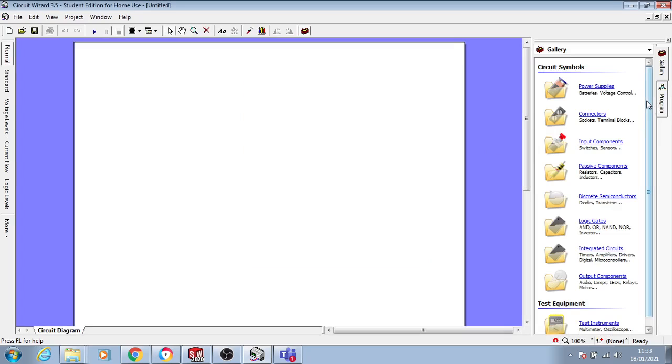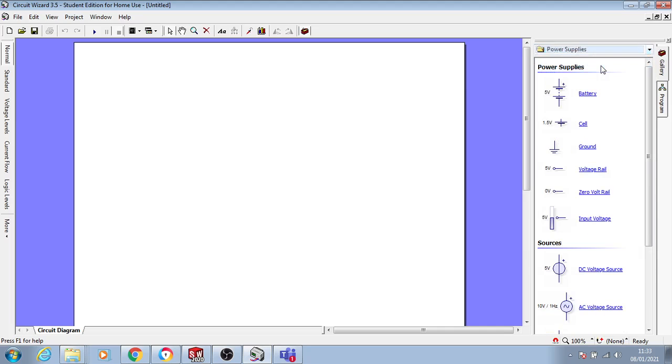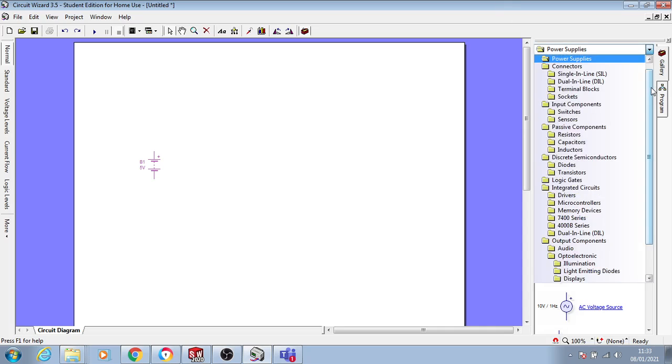As with the product design simple thing, we're going to need to connect up a circuit with power supply etc. So I'll go there and I'll just use a battery here, 5-volt battery. Now obviously I can draw a circuit. I can't actually finish this line, and I can only connect it up to something else, and I've only got a battery here, so I'll have to make a short circuit here to connect it. So best thing to do is, rather than burn out a battery like that, just get all the components that you're wanting to connect together in first.